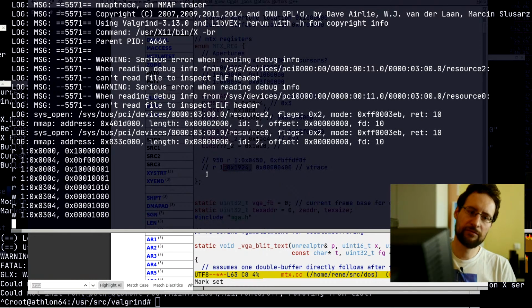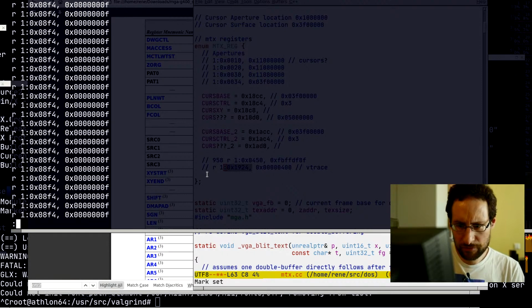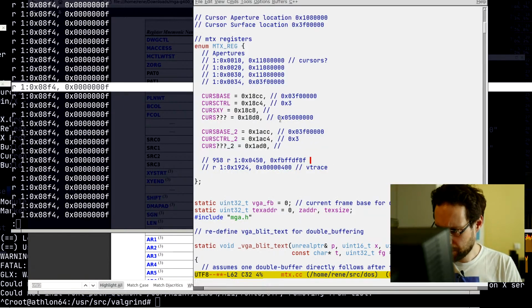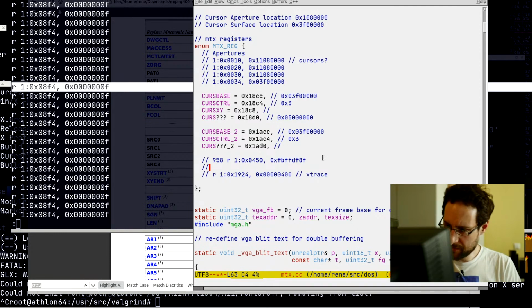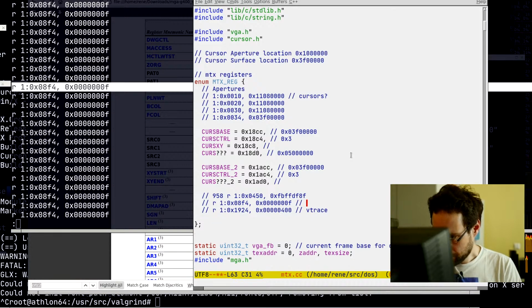And this is how, step by step, you would remove the stuff that you're not interested in, filtering out stuff you don't know. Here it's reading something, it's always reading F, so this might be some FIFO fill, like first in, first out, command FIFO stuff. We can also document this, and then it's always step by step documenting one bit at a time, and FIFO fill question mark retrace.